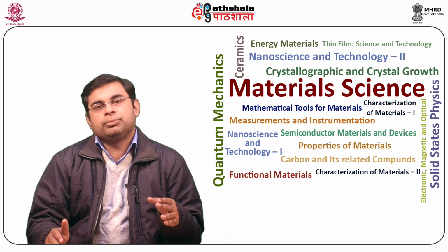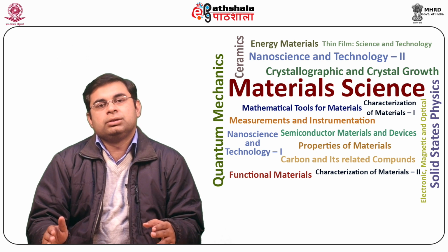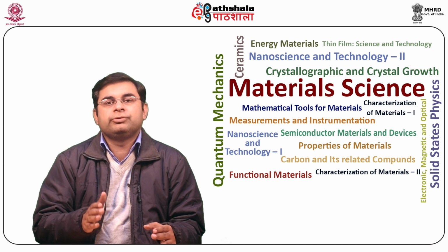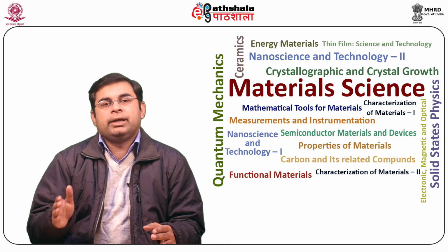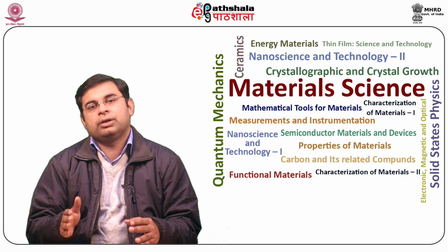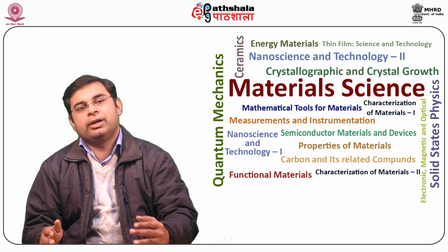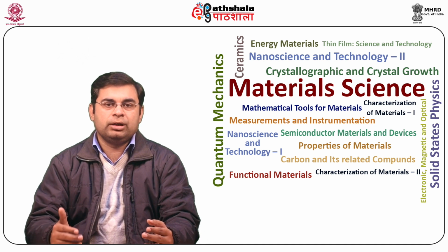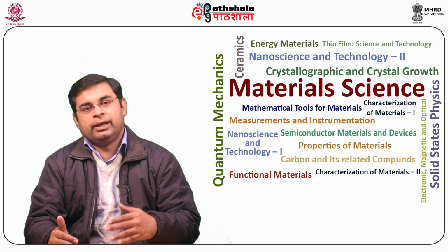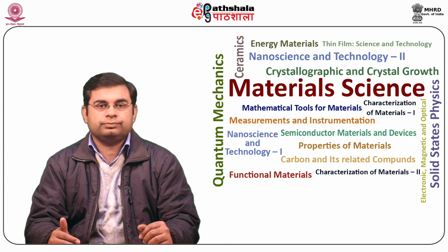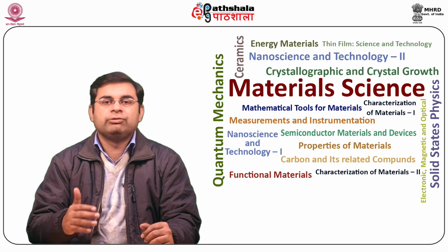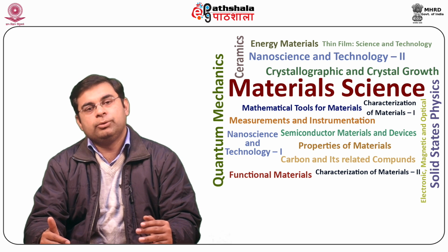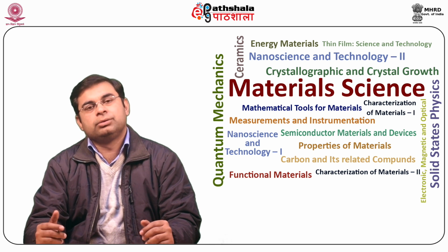Here m is the molecular weight of the semiconductor, Z is the dissolution valency, that is the number of charge carriers spent in dissolving a single semiconductor atom, F is the Faraday constant, ρ is the semiconductor density, and A is the contact area. The measurement depth of the carrier density is given by W equals Wd plus Wr.